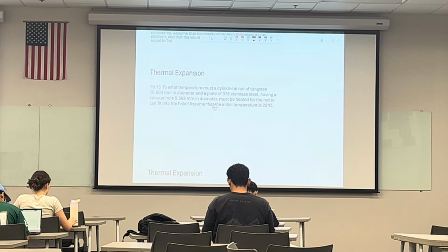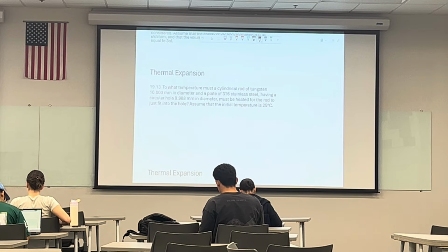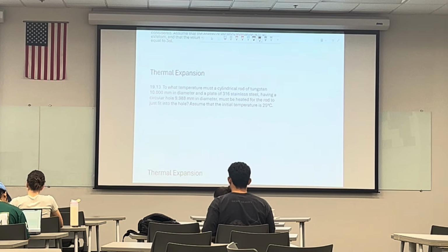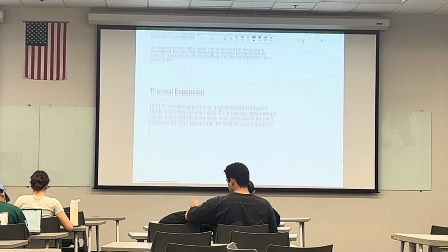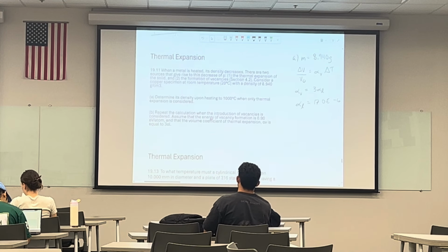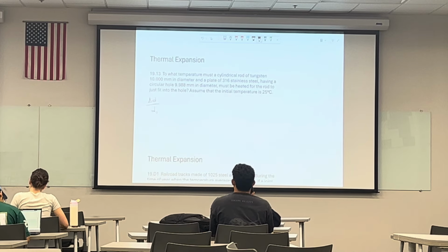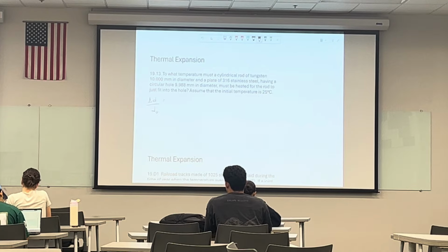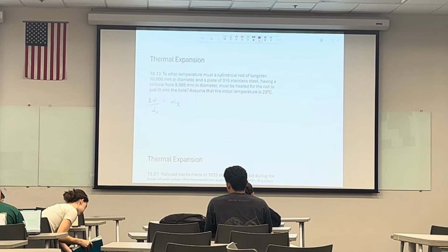The equation we need to refer to to determine the diameter: the change in diameter divided by the original diameter is equal to the coefficient of thermal expansion multiplied by the change in temperature.